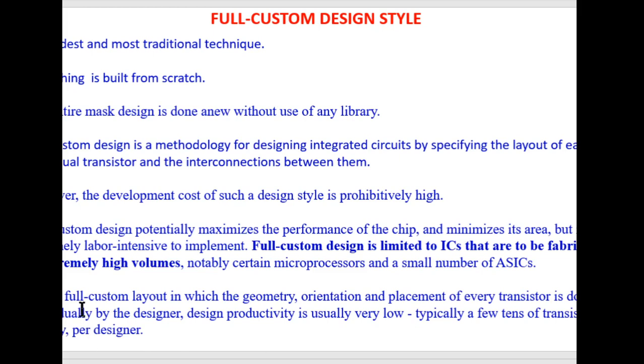So in real full custom layout, in which the geometry, orientation and placement of every transistor is done individually by the designer, design productivity is usually very low, typically a few tens of transistors per day per designer.